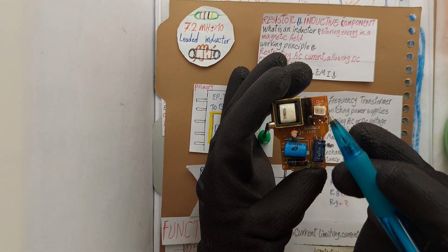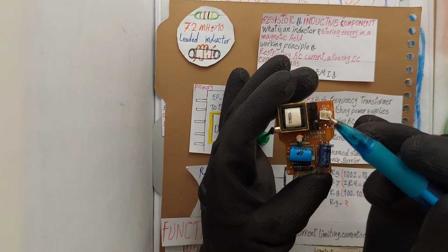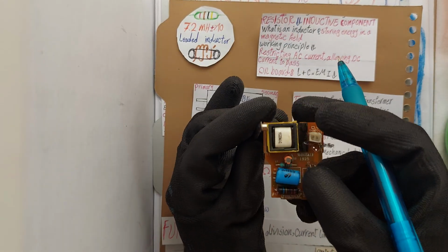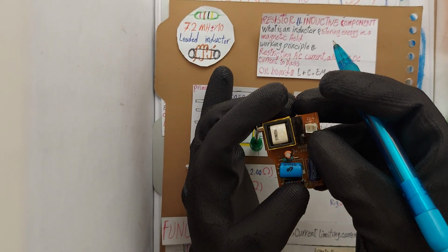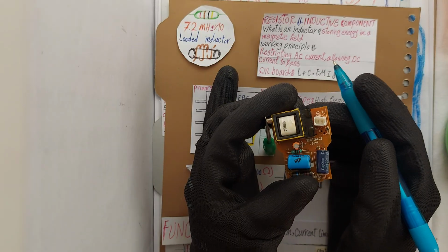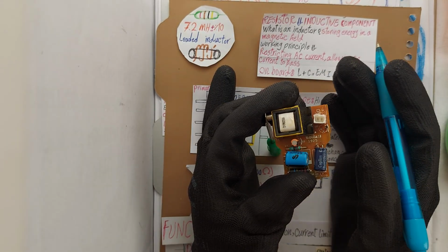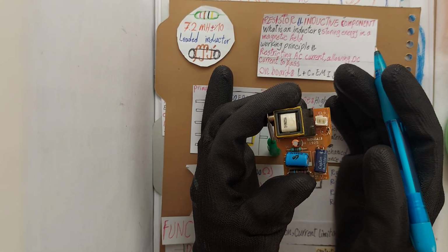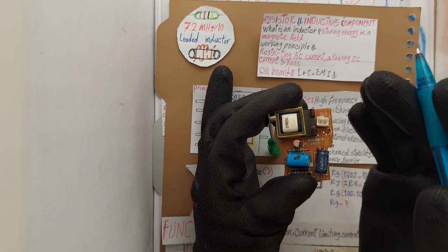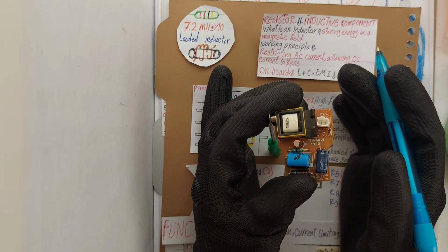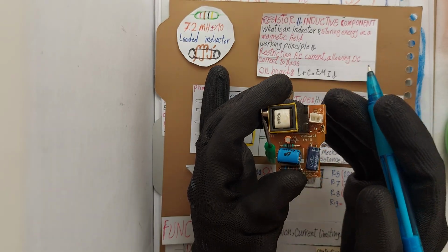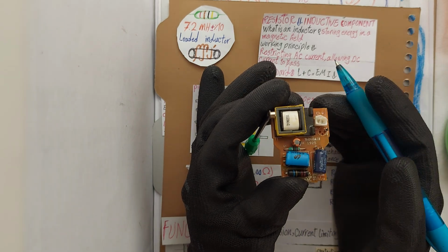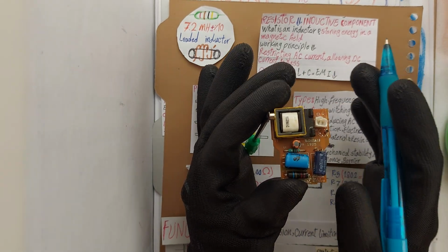Why is it mounted on black piece, as you can see here, here, and right here? Okay, because this base, typically made of resin or insulating plastic, provides mechanical stability, offers insulation, and is heat resistant, also acts as a barrier between high and low voltage sections. Topologically, it's likely a flyback type common in low power chargers and works with a switching IC.